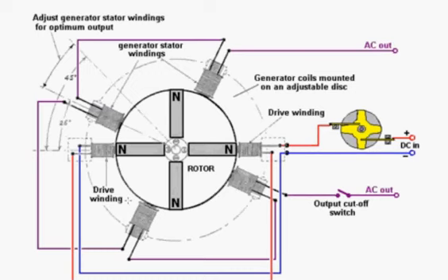Now, everybody will tell you, oh, you're going to lose power through eddy currents going sideways in those cores. Well, the answer is yes, you do, but you gain more than that, because the output from the coils is bigger than the eddy currents by a long way, due to the stronger pull of the rotor magnets.